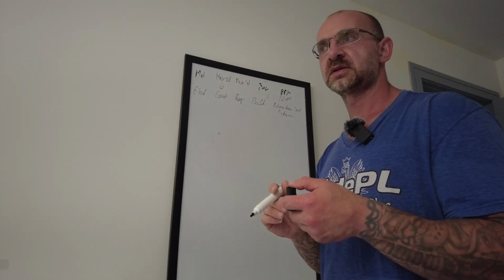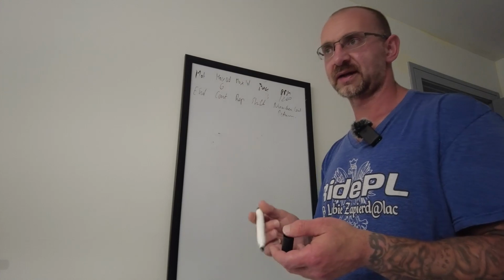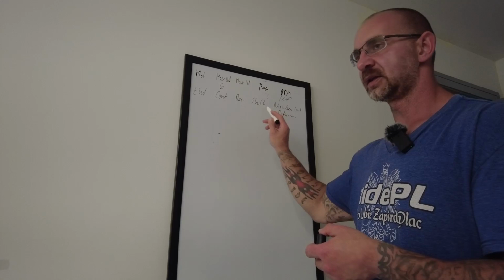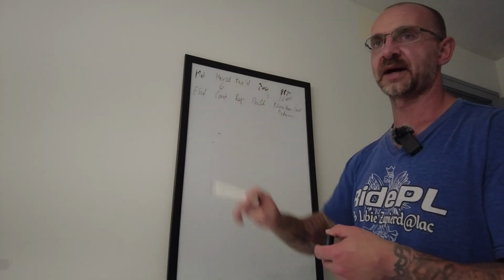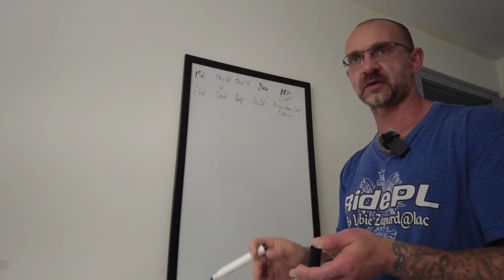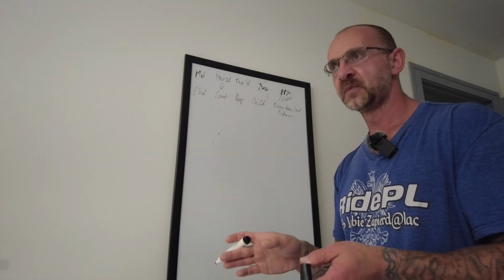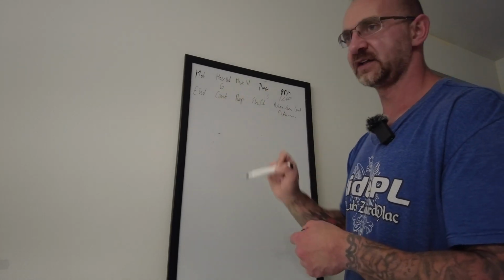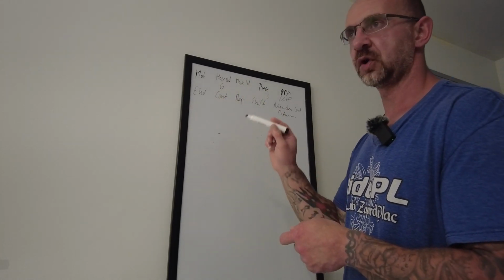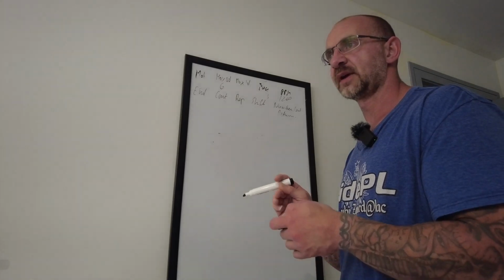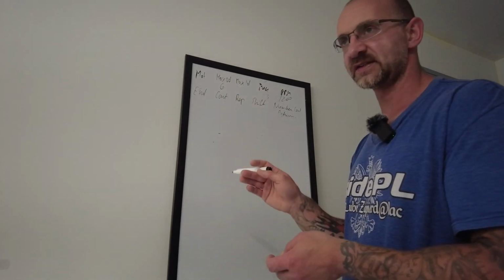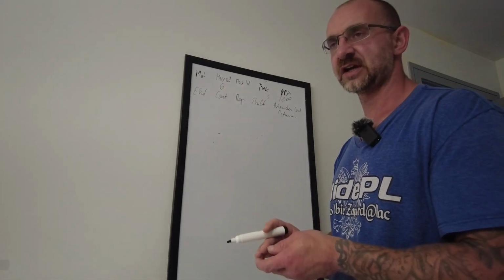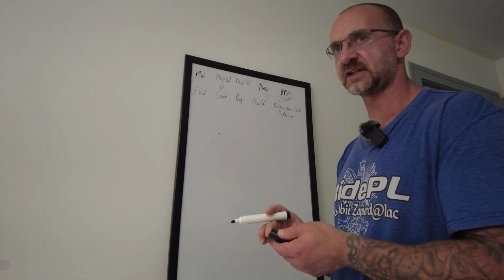So there are two ways to write a program. The way I do it is I fill up the header, and then I fill up the end unit, and then I start to add my body. So I add my facing, my OD turning, my threading, drilling, whatever that is. The reason I do that is, for example, if I add facing and then OD turning, and I have some weird radius and I want to trace it and see how it looks, if I don't have that end, she's not going to draw it for me, because she's going to look for that end.